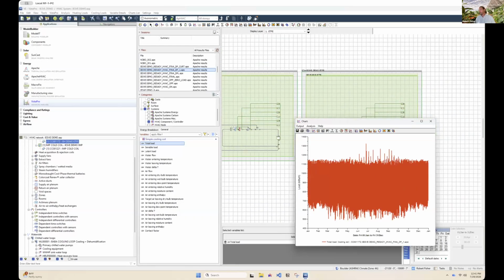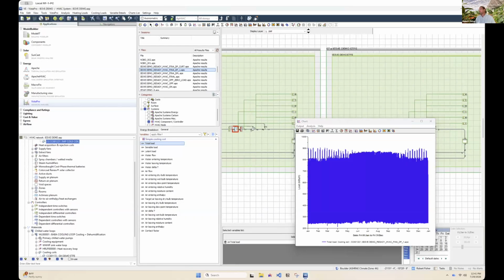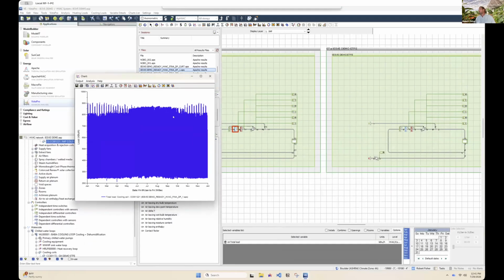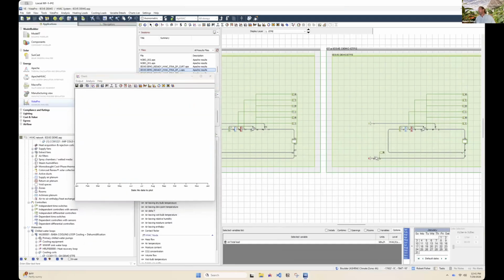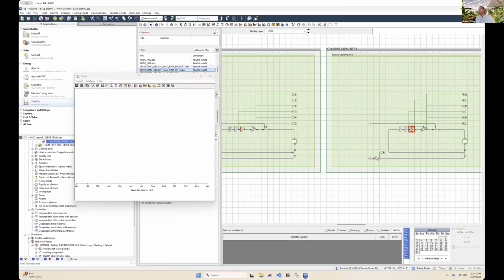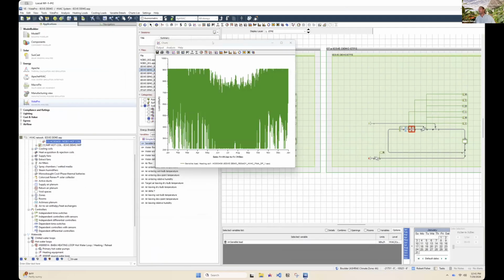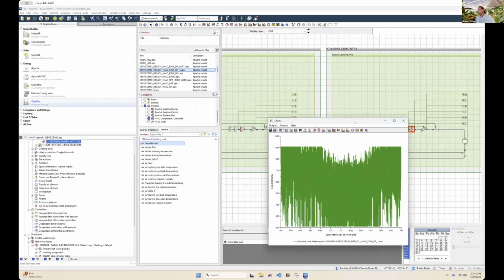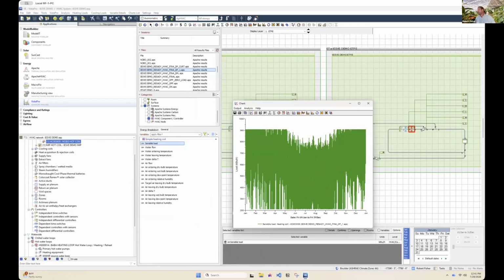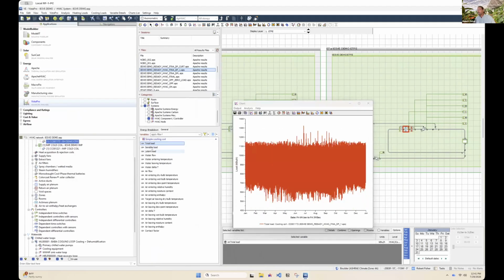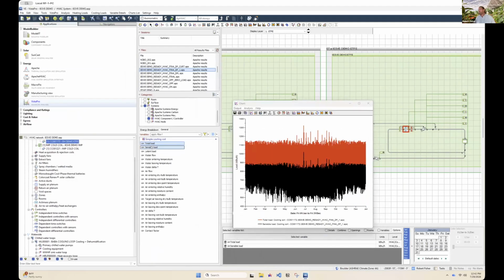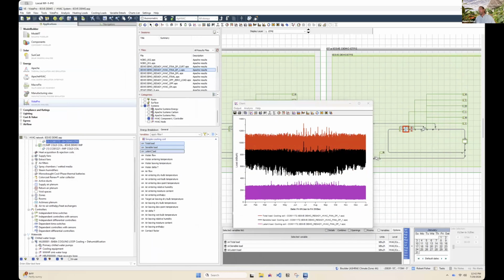Let's pull this one back up. It's a little messy there. Same thing for the HVAC heating coils. You can see the sensible loads. And I guess real quick going back, I want to see the cooling coils' latent load. I was trying to get to this. Total load, here's your sensible load, and then there's your latent load.